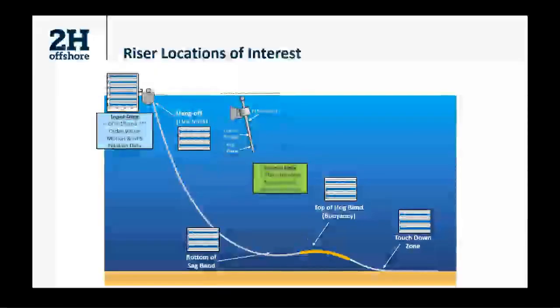The input data is often the 6 degree of freedom vessel motion and can be in the form of a combination of first and second order motion combined with GPS position data. Implicitly, direct environmental loading is included, as we just discussed. The response at these multiple locations can then be examined, specifically the two-plane bending moment and the effective tension.